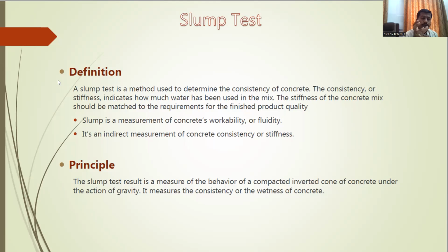That means we are going to use some cone that you call a slump cone. In that particular cone you are going to fill the concrete. I'm going to show the diagram for the same, so don't worry about it. And then you are going to lift that particular cone.